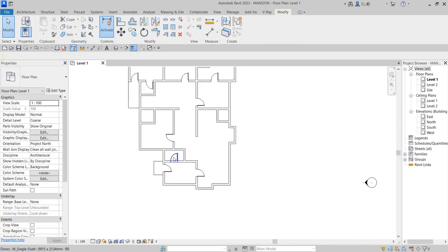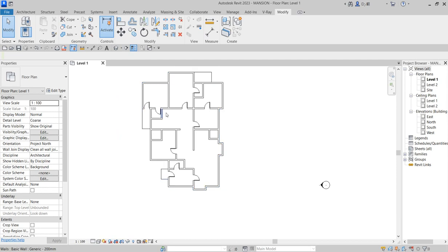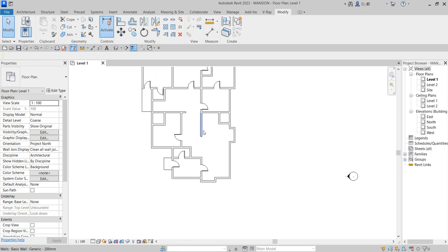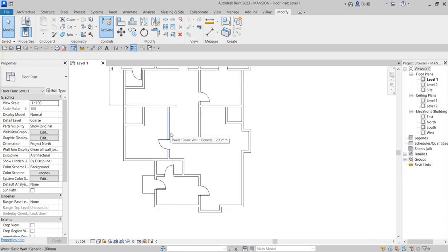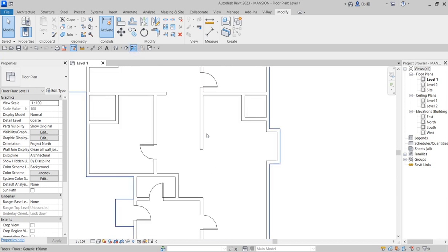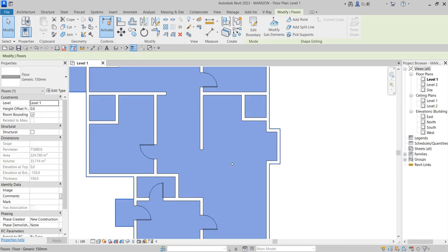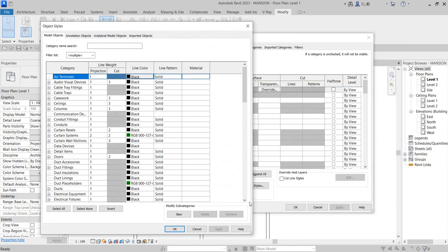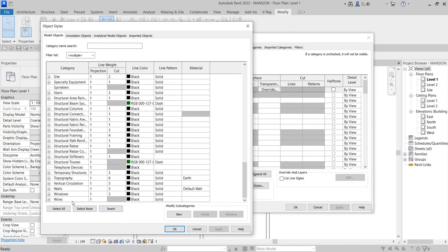As you do that, what are those things that you need to do again? The next thing you need is to bring the graphics of this into here, so that you will not be able to forget anytime you are doing your work. So how do you do that? You press Control, press VG, Visibility Graphics, on your system, and this pops up. From there you say Objects. From the objects you click, you go to Wall. On the wall, go to your cut width, and the cut width is what I want to increase.